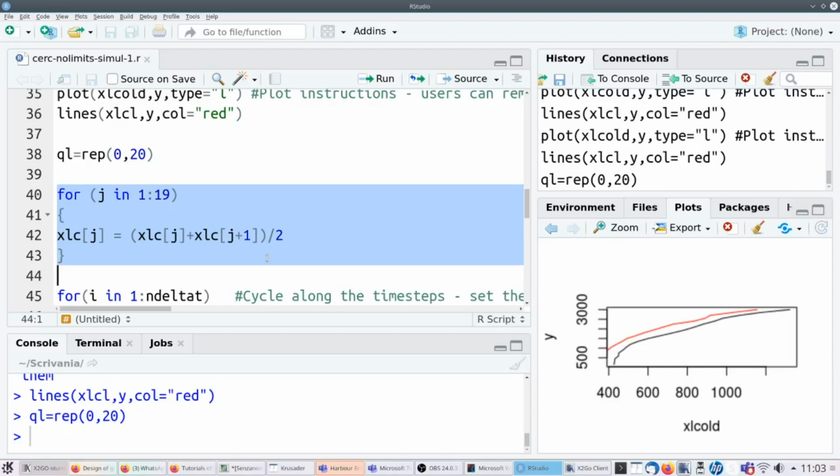You could take the average of 3 of them. Yes, this is true. I just worked with 2 because I know that I have to avoid local singularities, and I think that if I take the average between 2 it is just enough. But it may happen that you run your simulation and the model becomes unstable, which means that probably you need to widen your perspective even more. So it is something to carefully evaluate. So let's compute this smoothed version of the coastline.